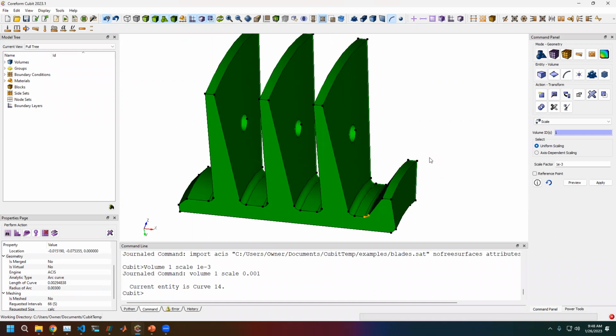So I'd scale up by 1,000, do all my meshing workflow there to get ample tolerance for Cubit to work with, and then scale my model on export. Cubit makes it available to you as a user to actually work with that absolute tolerance. It kind of exposes it.